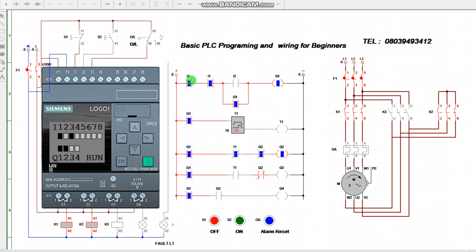Now, when this one closes, this is the main contactor. When this one closes, it will latch with this auxiliary bit. Then this same auxiliary bit of this is this 1, 2, 3, 4. So 1, 2, 3, 4 bit. This 4 bit is an integral part of this main contactor. Once this one closes, the auxiliary contact of this will take care of this and close the whole of this branch circuit, so that the power to the timer here can be energized.